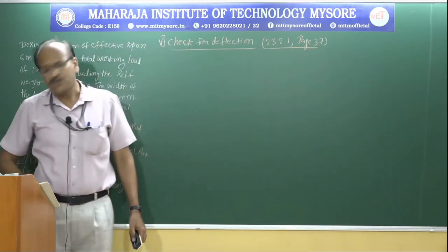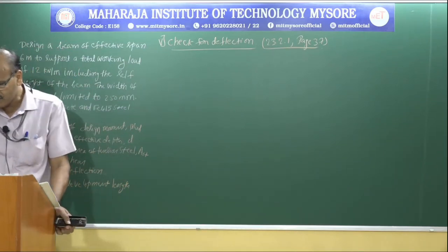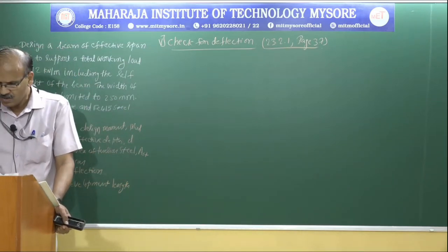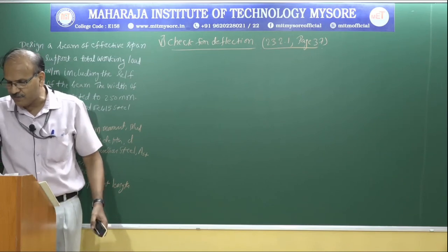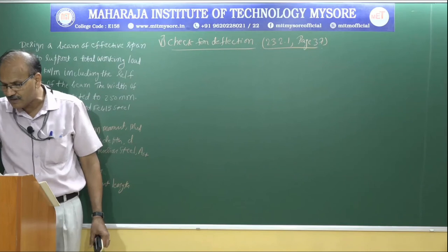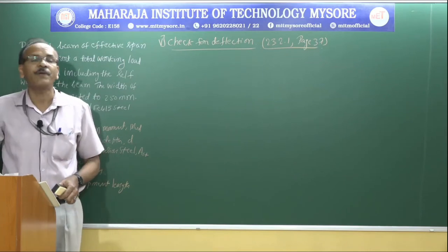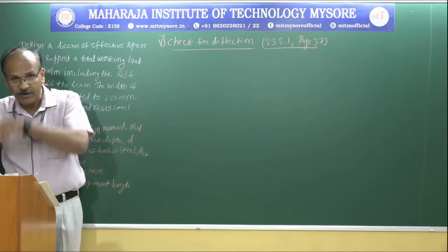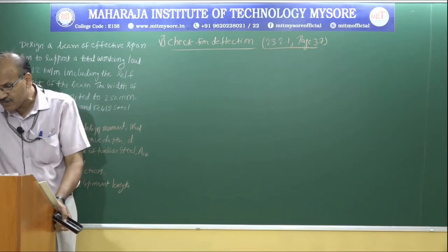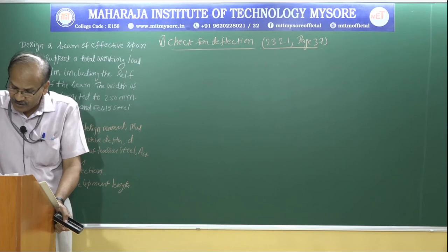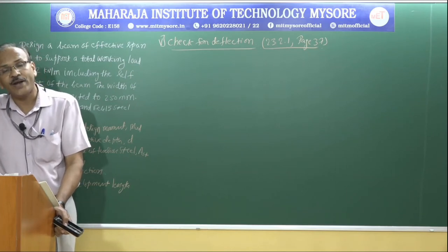So let me read out what that paragraph says. The vertical deflection limits may generally be assumed to be satisfied provided that the span to depth ratios are not greater than the values obtained as below. Okay, if I go to point A, so ours is a simply supported case. So simply supported case, it should not be greater than 20.